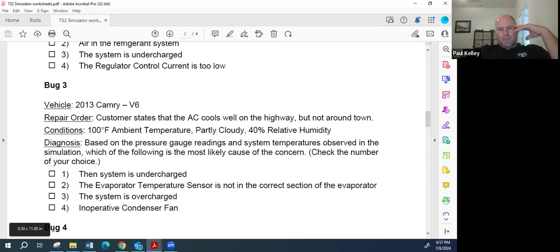And a voltage drop could be an issue, but for the cart not to move, it'd have to be a massive voltage drop, like an insane voltage drop. If the cart's a little slow, if it's a starter on a car and it's cranking slow and you see corrosion in the battery terminals, that could make sense. But you could measure that, right? So I took my meter out and I measured voltage drop, and I'm dropping well under a volt. I'm dropping like point something volts, not even 1 volt.